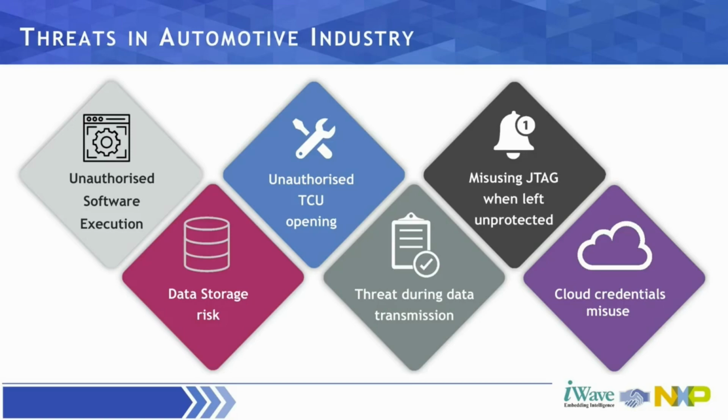The same applies in terms of your data storage, on your ECU or on your gateways. So what is the data you're storing and what is the level of confidentiality of that data? One looks to be very simple, but a simple action such as the TCU, the telematics gateway, opening to put a micro SIM inside the connector might completely open up your connected car to hackers, correct? So even your mechanical parts cannot be excluded as part of your security design.